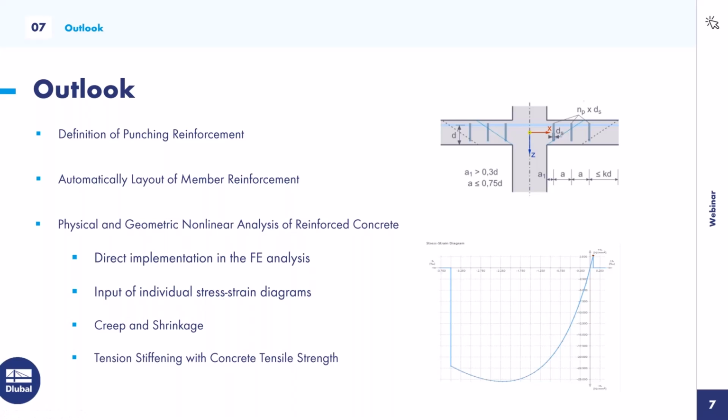On the one hand, with the modification of the Young's modulus, the so-called EEM method, which we already used in RFEM 5. And on the other hand, we will use so-called Kelvin-Maxwell chains together with the add-on Time-Dependent Analysis. With this new development, it will be possible to also consider the time-dependent material properties of the concrete in the add-on Construction Stages.